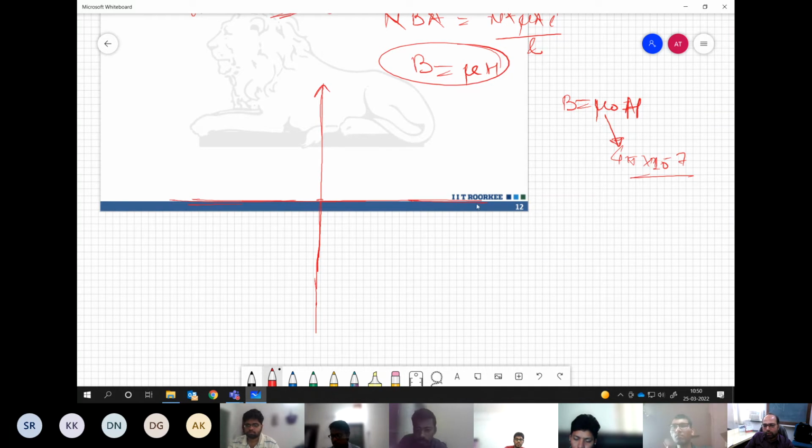If you keep your excitation, let's say I, or in other words H, on the x-axis, and your flux linkage, or the flux density, on the y-axis, what we will find is that as you increase the excitation in any coil which has an air core, you will generate a certain flux density, but it will be a very small number.